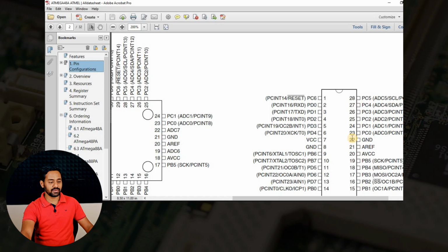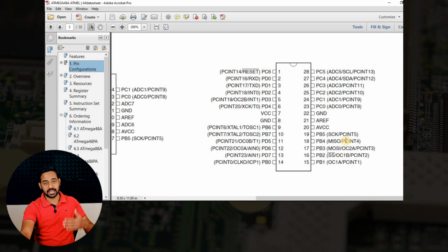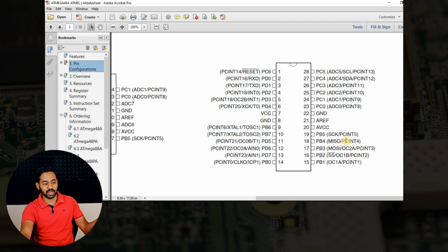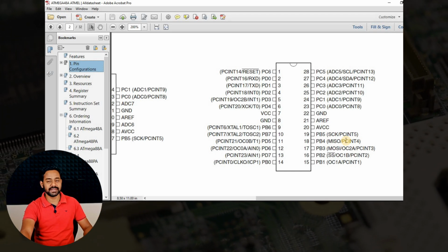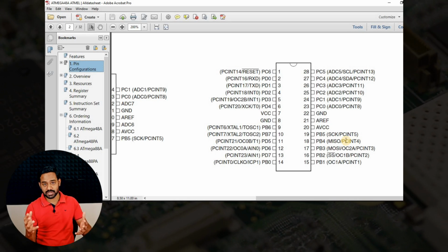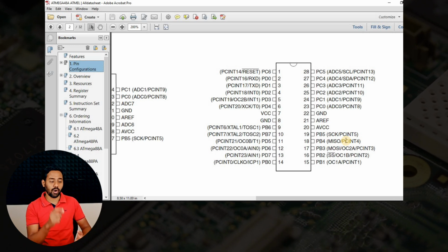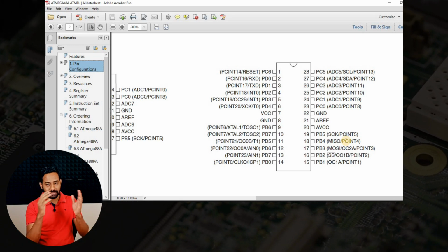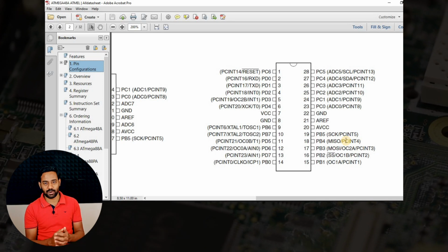One is going ahead with the same design as given in the datasheet as per pin number, like pin number 1, 2, 3, 4, and giving all the features that are given on the schematic symbol representation in the datasheet. Or we can categorize the pins based on the port number, the power category, or the electrical property of those particular pins and make them aesthetically look good. Choice is yours, but I prefer to go with the second option.